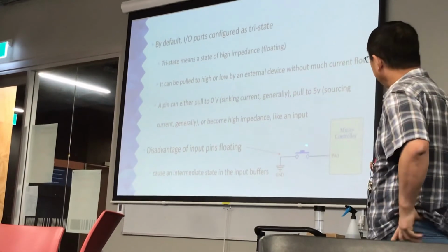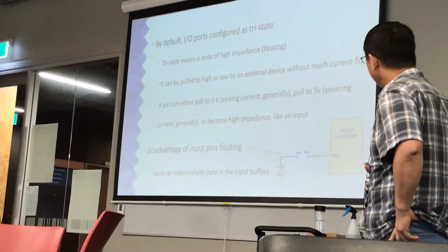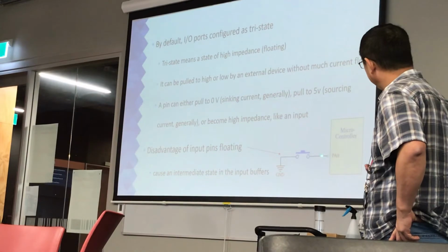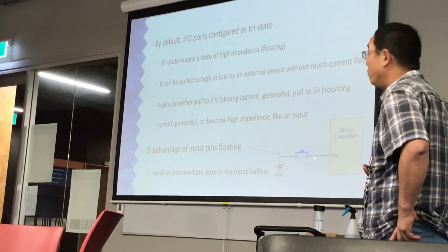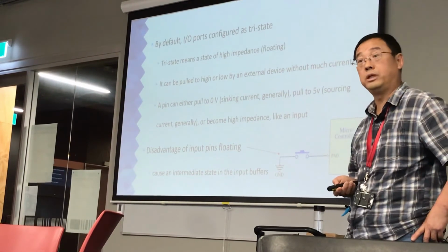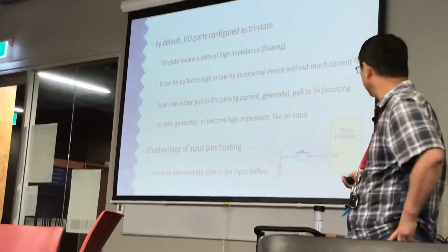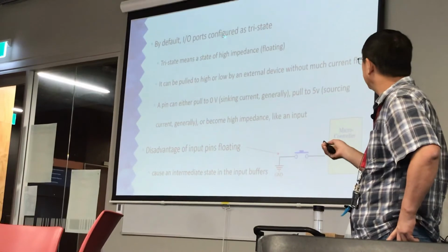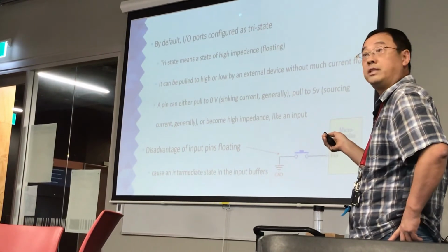But if the button is not pushed, nothing is connected to PA0, and we call this pin floating. It is tri-state.